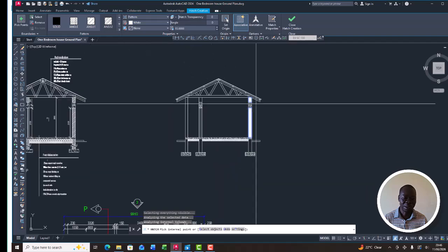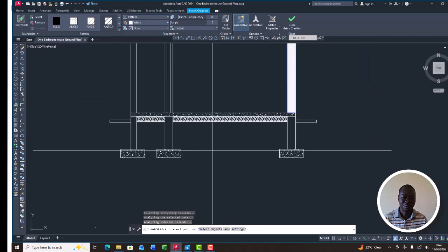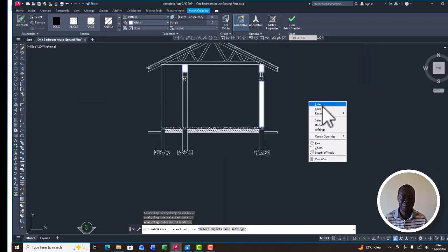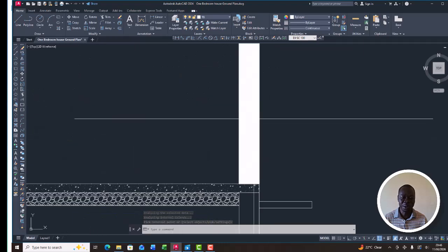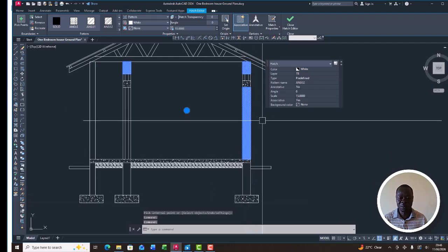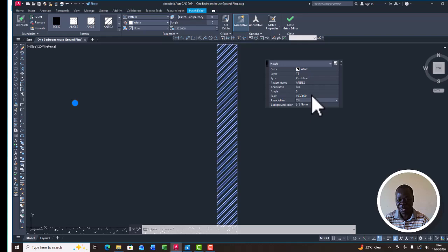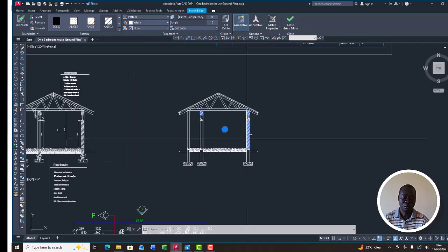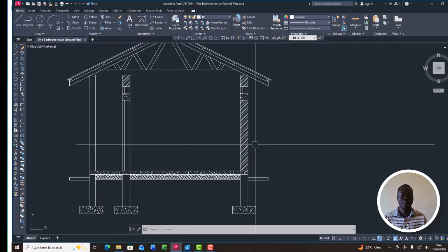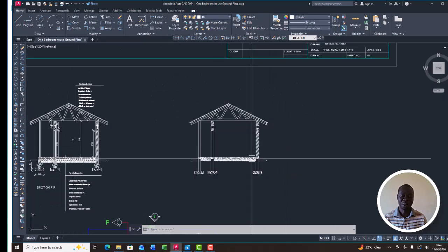Then I ask here on the foundation side, let me first leave it. I'll do it later because I want to show the foundation line here. So I can double click to change the scale. It's very dense. I can try scale 150, hit enter. Maybe I do 200, enter. I think 200 is okay. So we leave it at scale 200. You see now, this part and this part, they are now looking alike.